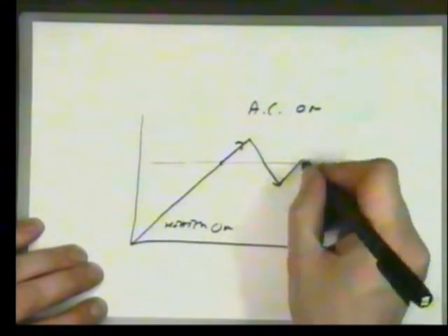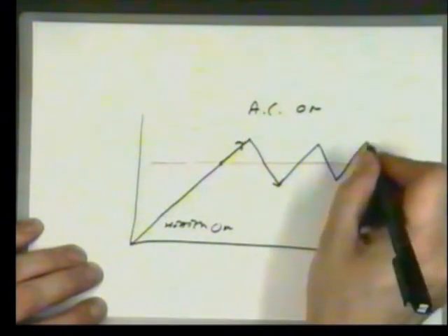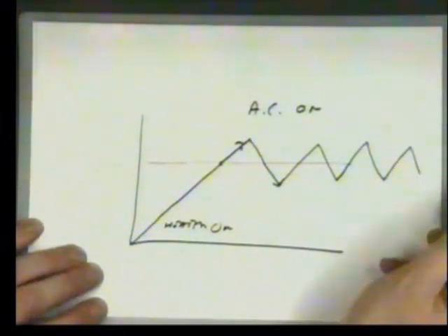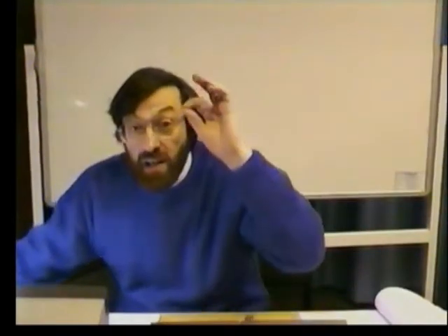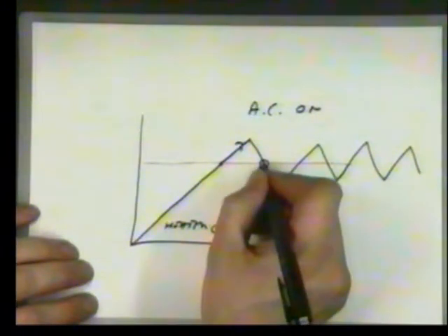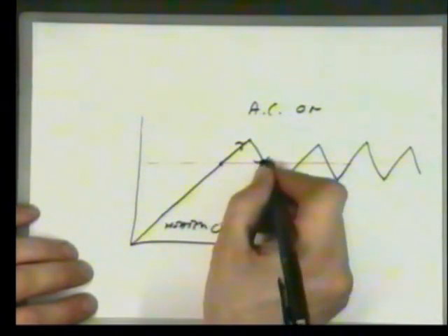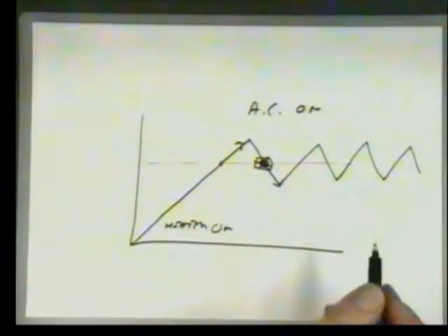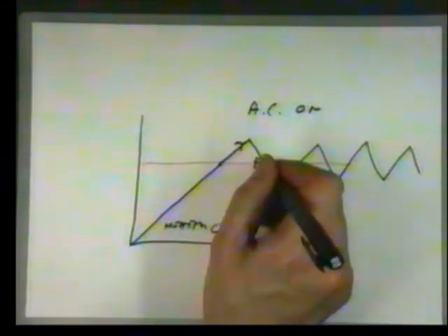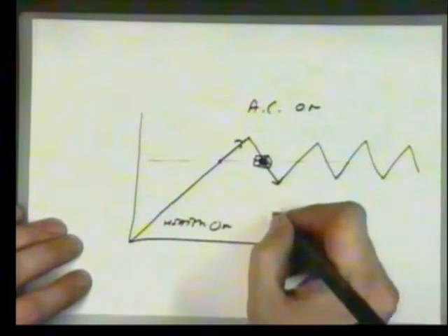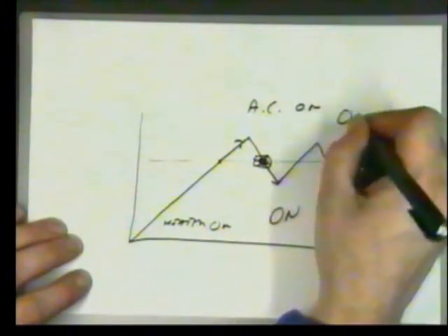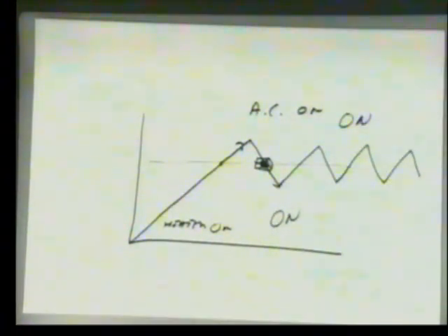So what you can have happening is, again, the identical response characteristic. But think what happens at the singular point around the set point itself. And bear in mind, there's always a margin of error. It is actually possible to maintain the set point by having both the heater and the air conditioning. They could both be full on fighting each other to push you into the set point.